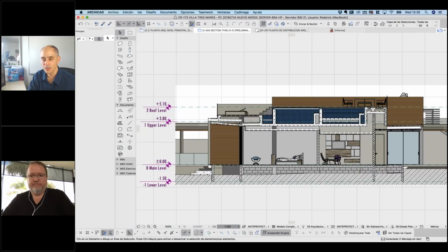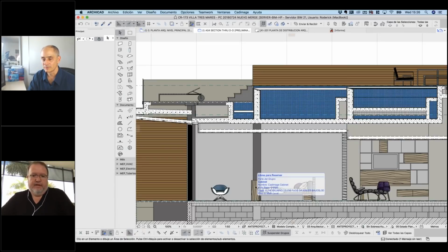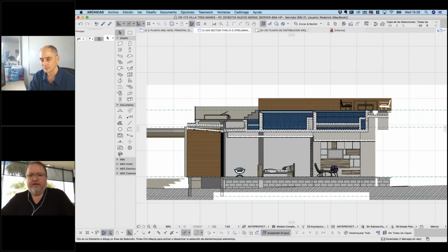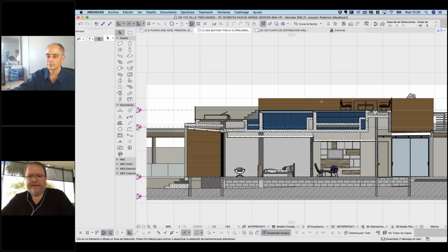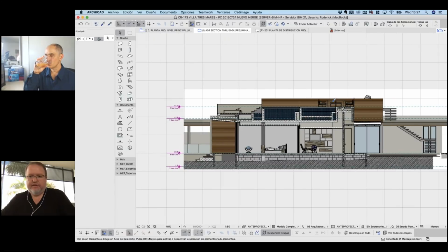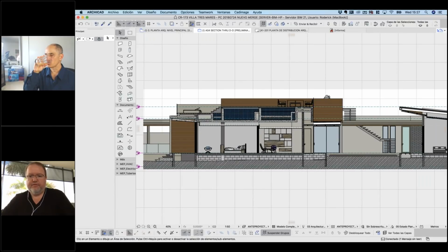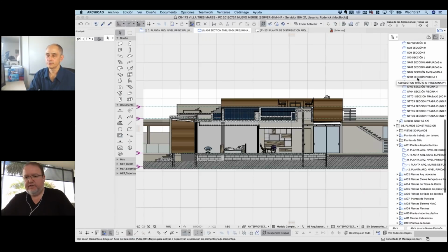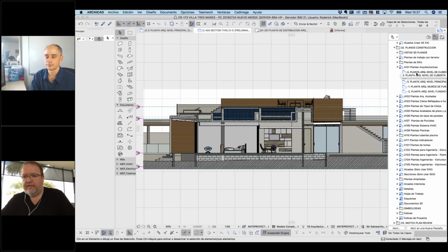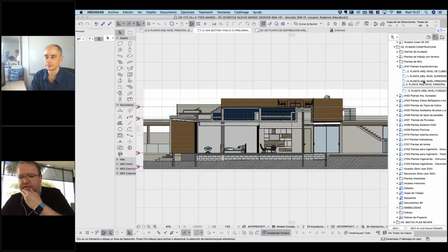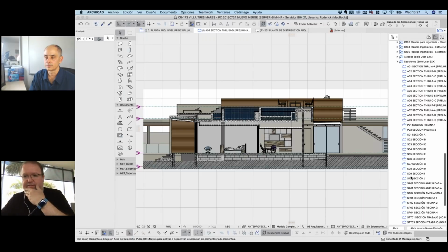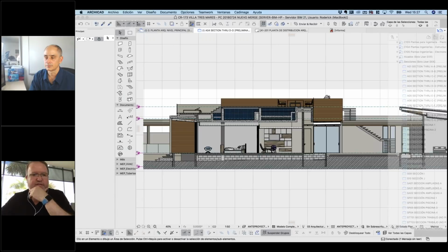So you've got, for example, furniture in there for this presentation type of section, as opposed to a construction section. Yeah, so I've got furniture in here. I've got colors turned on for my vectorial hatching, so that it's more client friendly. Just for the purpose of the presentation, the client will be able to understand the project much clearer than from the other one. If we switch back to the construction one that I was looking at, and forgive me for taking some time on this, but I usually don't work with multiple tabs because I feel that they start taking a lot of memory away and slow us down.